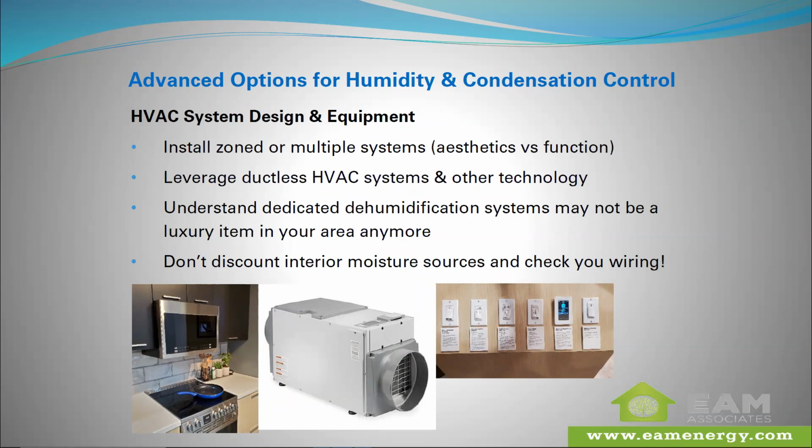Jason and I were talking about this before the call. Cooling expectations from people have gotten really picky in recent years, to the point of expecting these crazy 30, 35 degree temperature differences from the outdoor temperature, and then also not wanting to see any condensation or anything like that. So you just may not be able to deliver quality dehumidified air under all circumstances without a standalone dehumidification system.